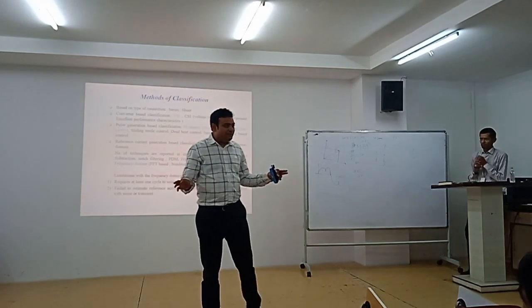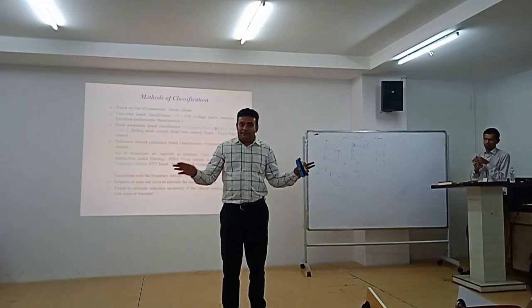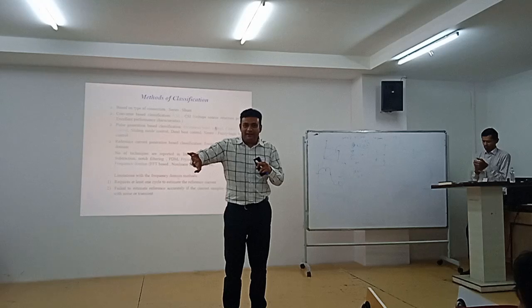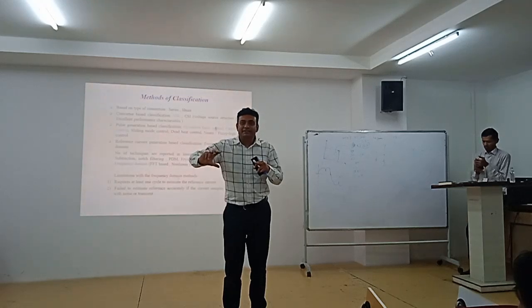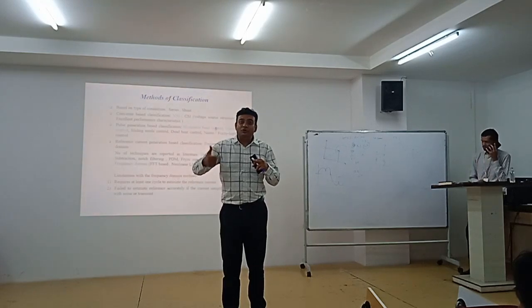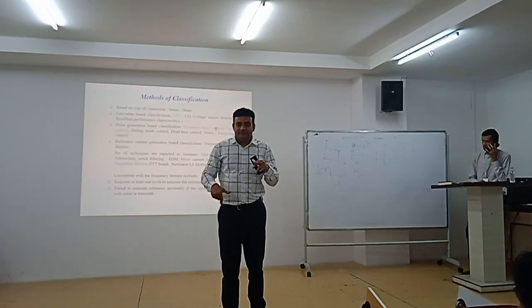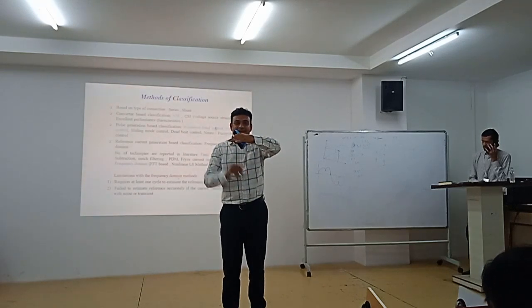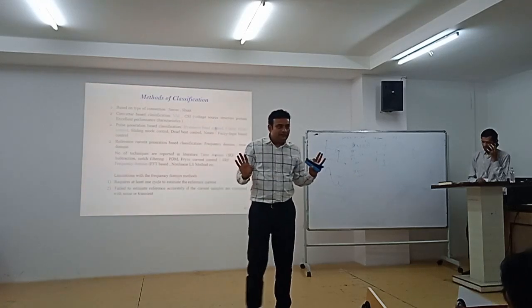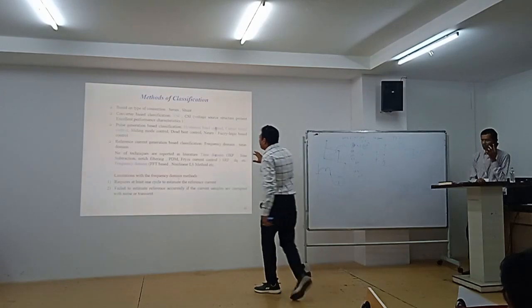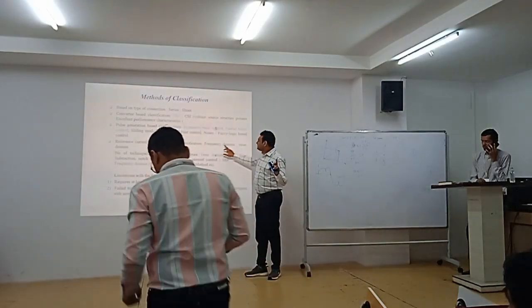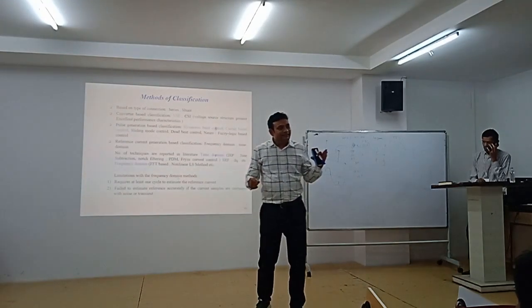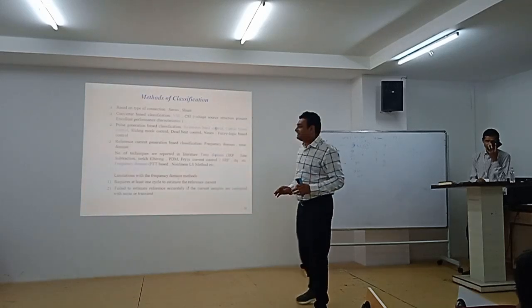For example, in our system, if we take a particular spectra, right, you remove the fundamental component, rest of all are harmonics, and those harmonics are to be compensated, right? So you have to produce a reference current 180 degree out of phase, right? So somewhere you cancel, somewhere you double, right? So reference current generation has major methods in frequency domain and time domain, and the third is wavelet, time and frequency combined, right? Okay.